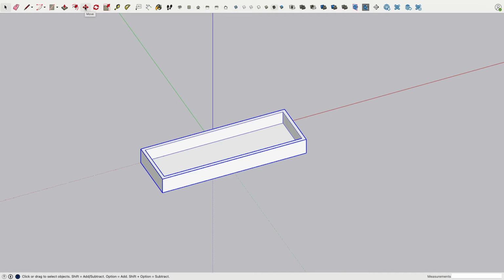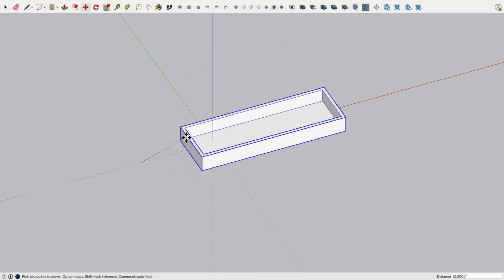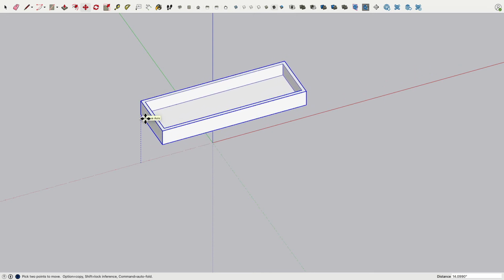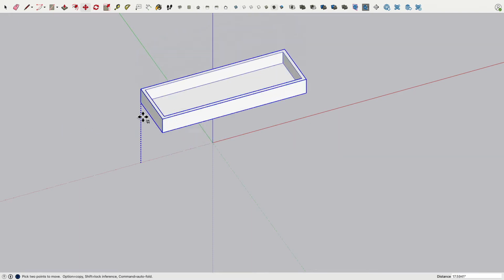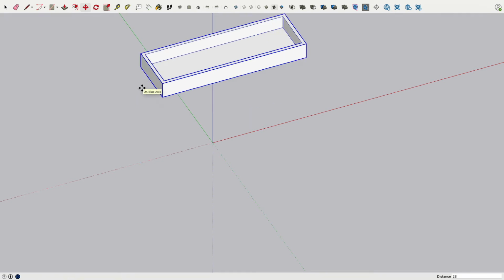So we can go to move, and here, actually, the top part should be at 32, but we measure from the ground. So actually we go here to this bottom part, move this up. You also see how I'm moving this left and right. And then here is actually, this is blue. Or to make this easier, press the up arrow key. Now I can only move this up along the z-axis by 28 inches.